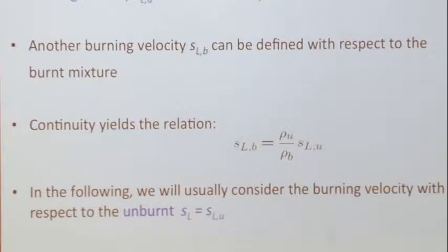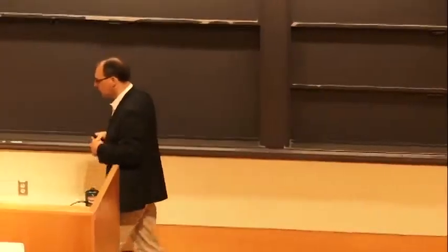Typically you assume it's equilibrium, but there are uncertainties related to this. It turns out when you have non-unity Lewis numbers, or strongly non-unity Lewis numbers, the temperature in the burn is not really constant. It does funny things. And then the other thing is you have radiative heat losses maybe, and the radiative heat losses also lead to a decrease in temperature and an increase in the density. So that's one of the major uncertainties of this.